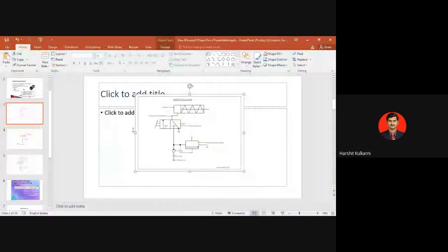When you go for left envelope, P can go to B and A can go to T. In the sense, when you go for left envelope, first retraction will take place, and when you go for right envelope, then extension will take place. You can exchange those positions also. This all depends on your requirement and application. Remember this one. When you go for a hydraulic circuit, there is a lot of flexibility. So some guys take a 4 by 3 valve, plug one port, take it as a 3 by 3 valve and use it for a single acting cylinder.